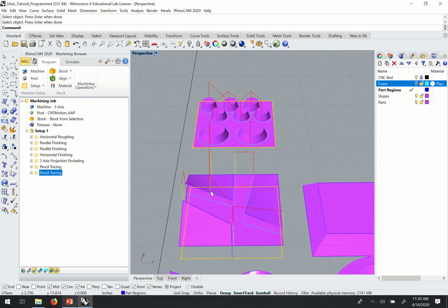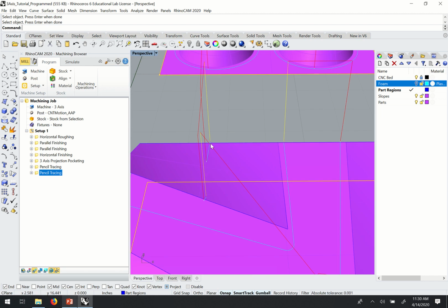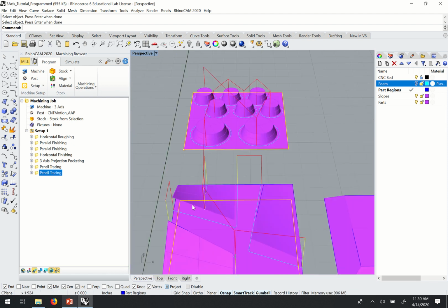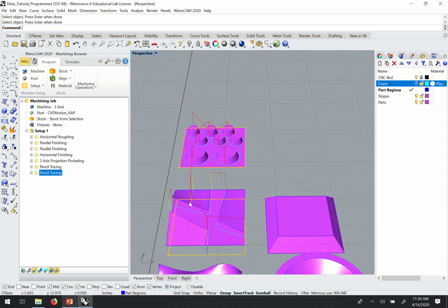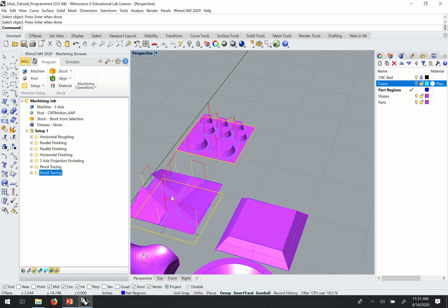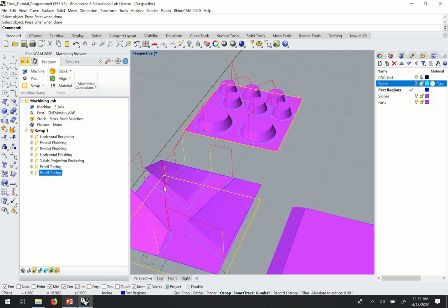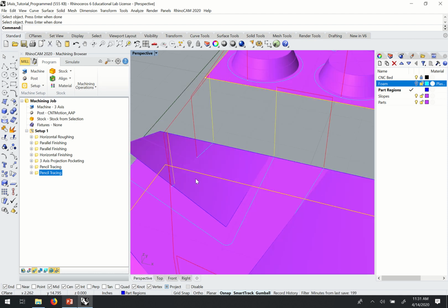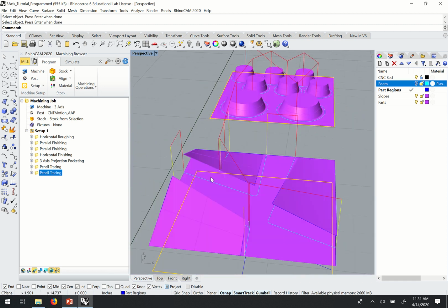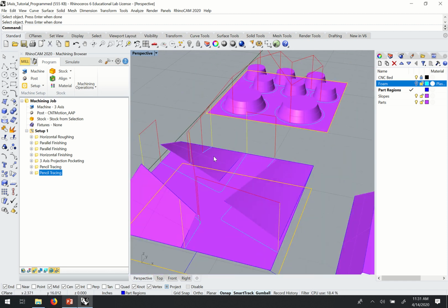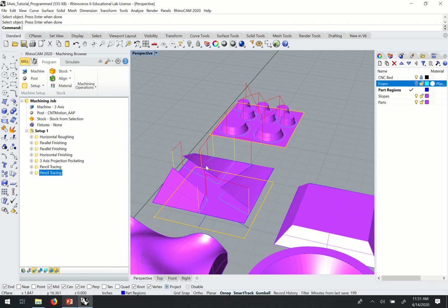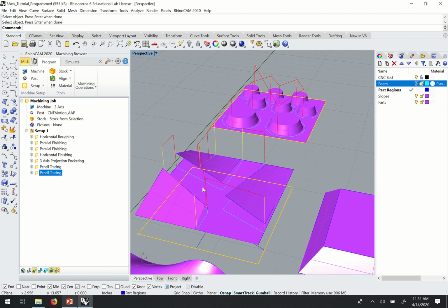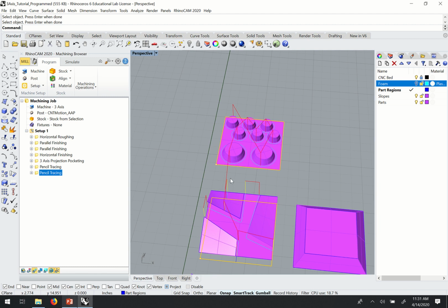And so one way that it can be problematic is it can sort of add toolpaths where we don't necessarily want them, and so we may need to look at other ways of cleaning up edges if the pencil tracing is giving us either curves that are not necessary, that may make the process take much longer, or maybe curves that will affect the surface finish, and we can't really omit them because of the way that the algorithm is generating the toolpaths.